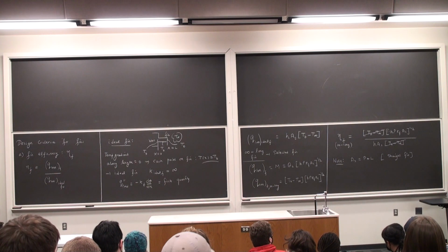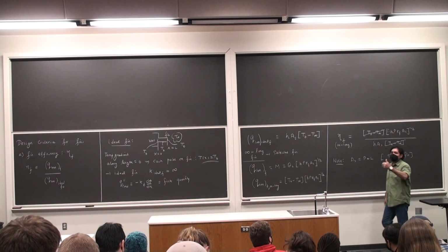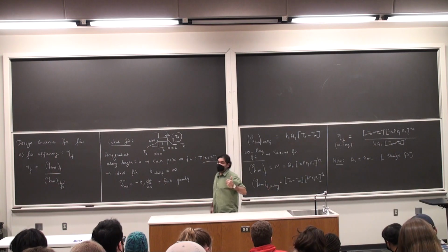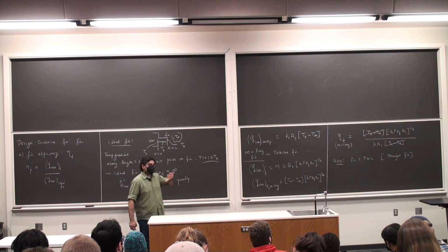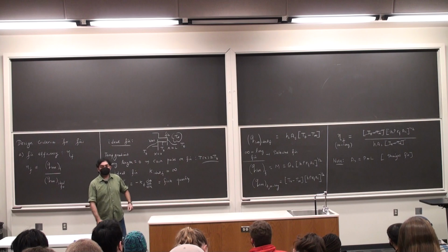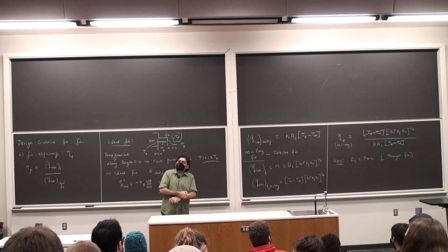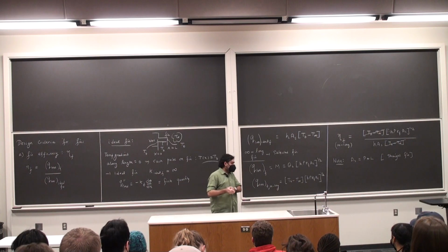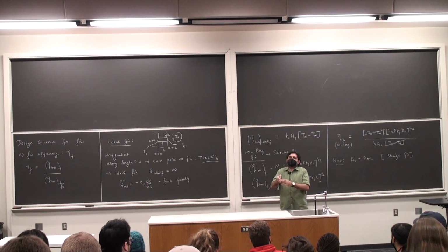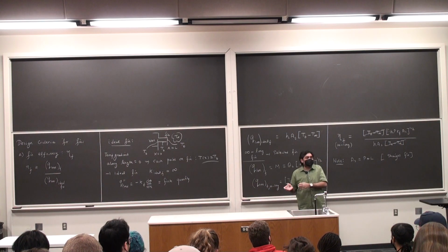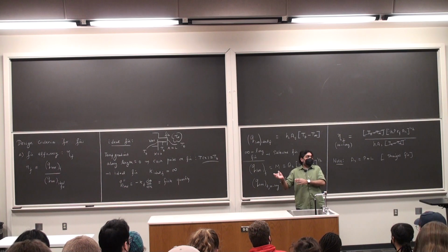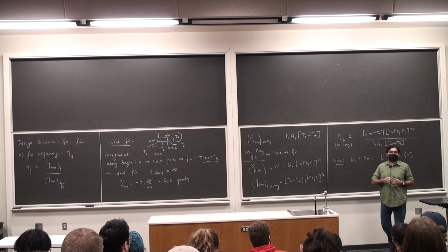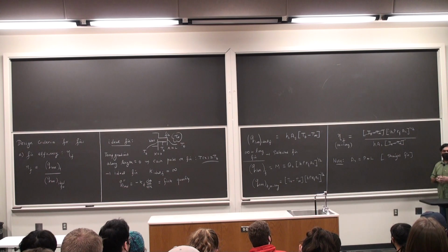Infinitely long, so the tip is essentially insulated, so I'm not including the surface area available at the tip for the convection heat transfer. Okay? So this is just the surface area besides the tip. If you are looking at a real situation, then you'll have to use what is called a corrected length. Your textbook goes over that, we're not going to use that. A corrected length essentially takes care of the fact that in real fins, the tip need not be insulated, so you have to include that surface area as well for convective heat transfer. We're not doing that. Okay?